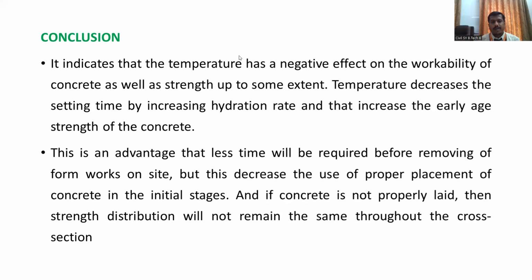Sir, is heat of hydration good or bad? See, heat of hydration is a continuous, long lasting process which happens in the concrete. If there is no heat of hydration, how is your concrete going to gain strength? Mayur, I think Mayur has asked me that question. Is it good or bad? See, your concrete is not going to achieve the strength. It is not going to harden unless there is heat of hydration. So heat of hydration is a must, and it's a long lasting process which happens in the given concrete. Okay. Without heat of hydration, how can we imagine the concrete is going to be